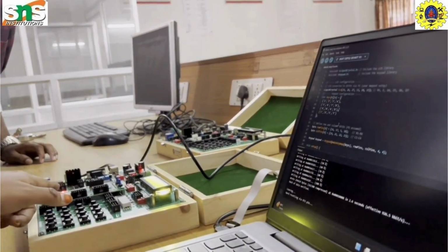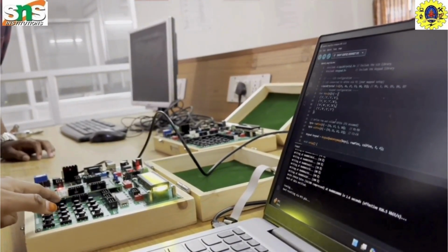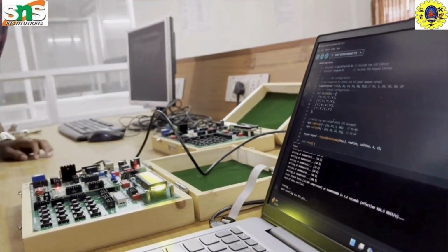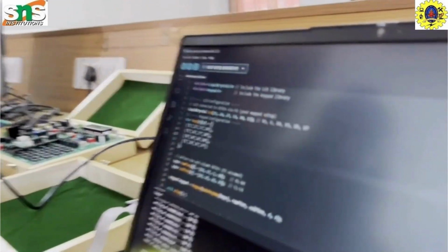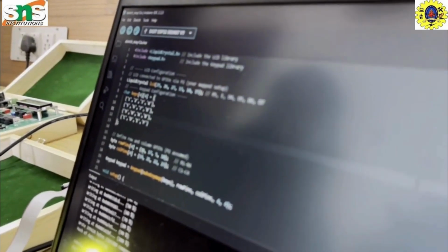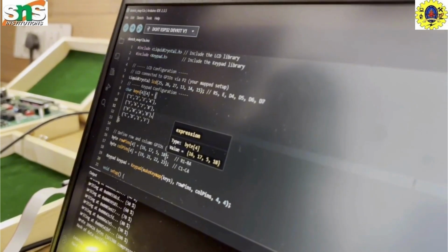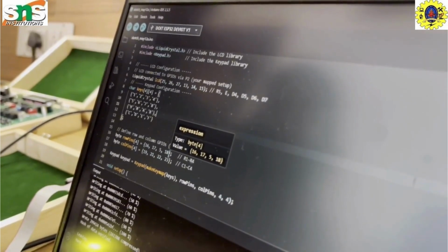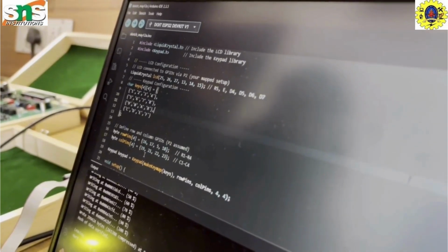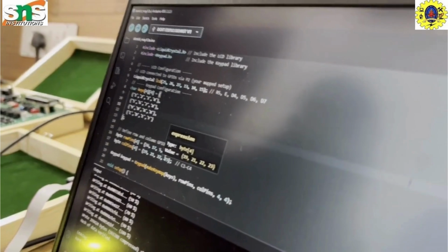Before getting into the hardware configuration, I should mention what the rows and columns are. So I am mentioning the row pins, which are 16, 17, 15 and 18. These are the pin configuration for the ESP32 and 4x4 matrix. And likewise the column pins have been described here.